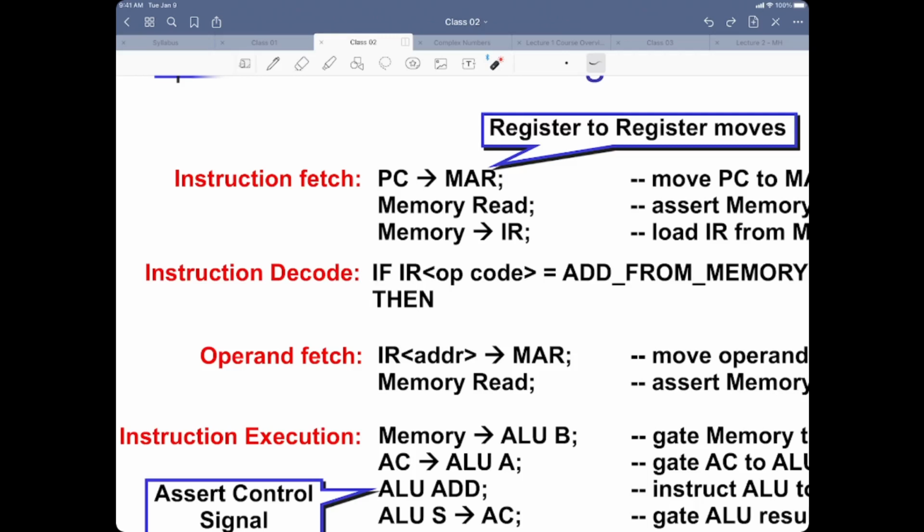Well, the designer is going to write a programmer's manual or a reference manual in which they're going to list out: I have designed this computer system in such a way that 000 corresponds to add from memory. 001 corresponds to halt. 010 corresponds to OR, and so on, right? So somebody must have designed it, and they put all of that information in a reference manual, and then the programmers or the people who are writing these RTN, they are going to refer to that.